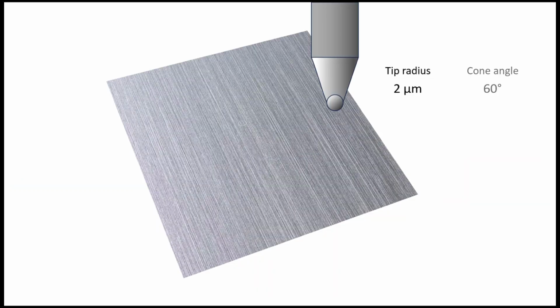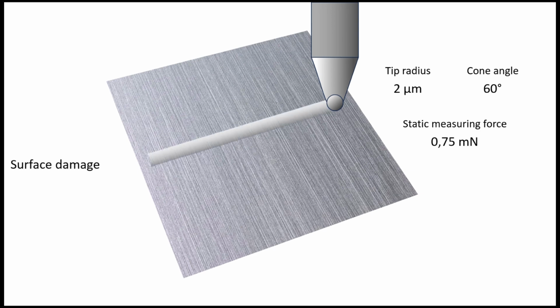Most 2D profilometers use a contact stylus with a small spherical tip of known diameter. This makes them well suited for metallic parts in mechanical and automotive industries. However, the stylus applies a local force that can sometimes scratch delicate surfaces. Another drawback is that the tip trajectory is sometimes not perfectly straight due to torsion effects and lateral pressure caused by local hills and dales of the surface. The result is that points are not sampled at the expected XY position, leading to uncertainties.